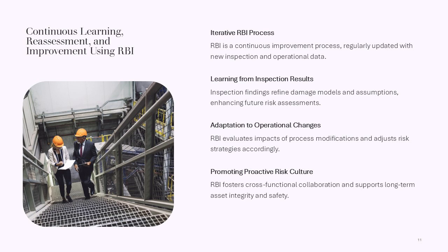RBI also supports adaptation to change. Modifications to process conditions, feedstock, operating limits, or equipment configuration can significantly alter risk profiles. RBI provides a structured framework for evaluating the impact of these changes and adjusting inspection and risk management strategies accordingly.